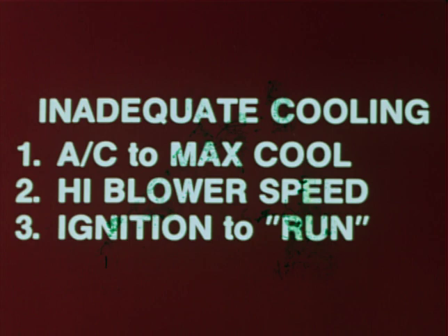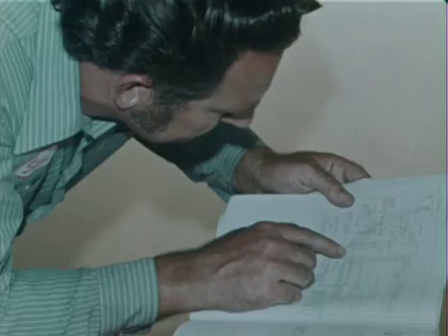Turn the ignition switch to the run position and listen for the click of the compressor clutch and the sound of the blower fan. Remember, since this is a 1974 Vega you are working on, you must wait at least 25 seconds for the clutch coil to engage. In this case, the blower works, but the compressor clutch does not engage.